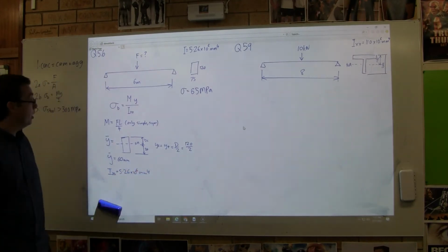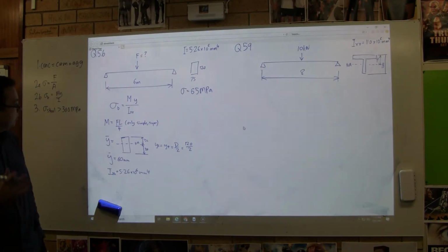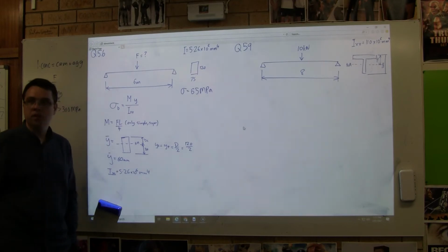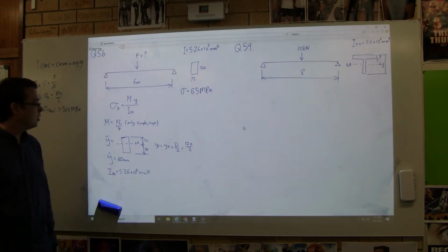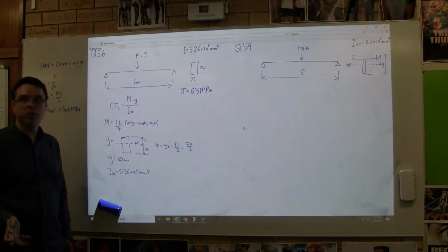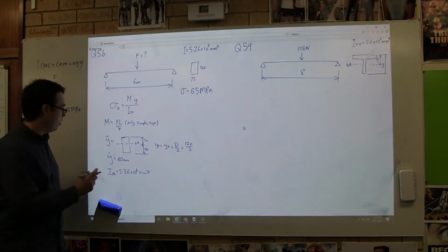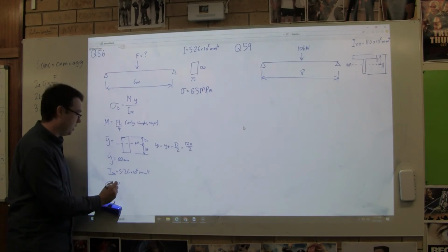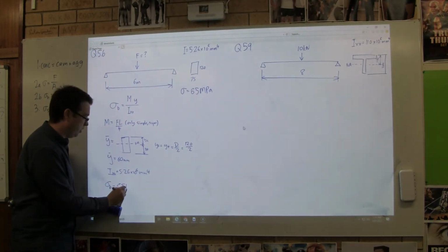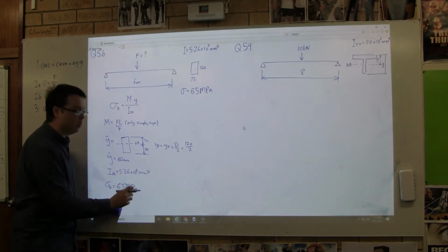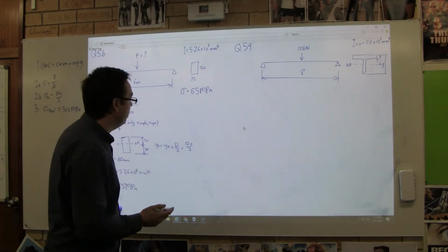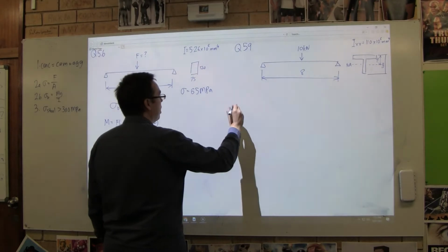Okay, so we've got our information, we're happy with all that. Now let's see what we need to do. We need to find F, right? We need to find F. So what we could do is just put the formula in now, right? They've given us sigma B, the bending stress. The maximum bending stress can't exceed 65 megapascals. We'll assume that's a factor down, so maybe half of what the actual material can allow. So I'm going to write all that formula in.